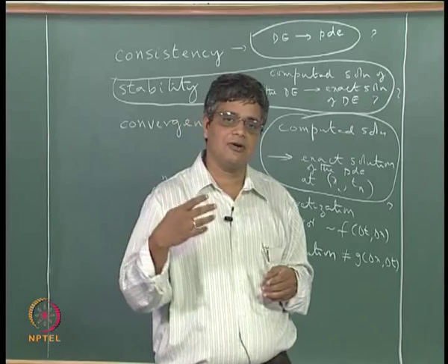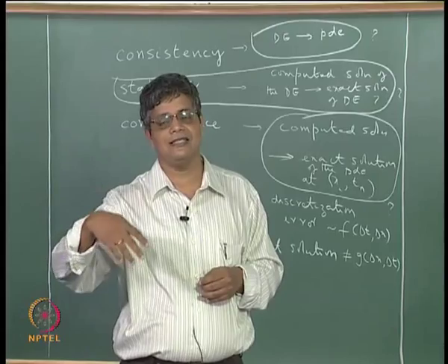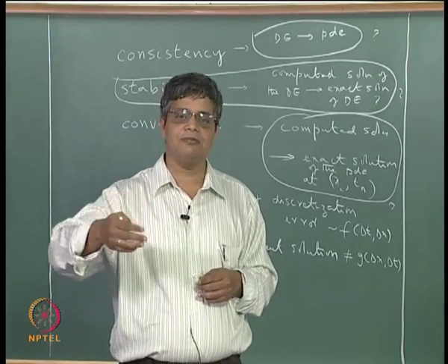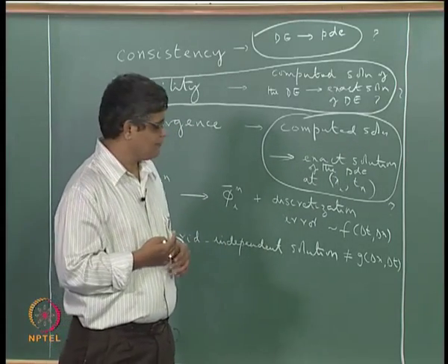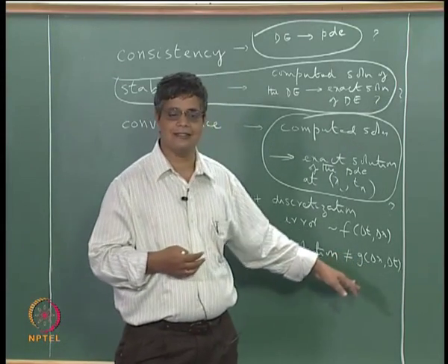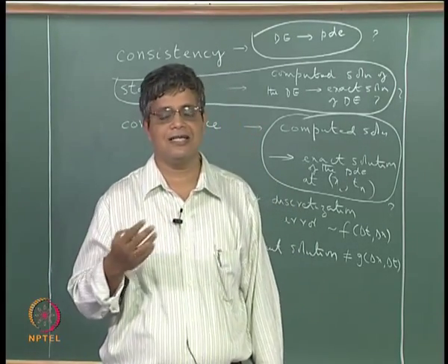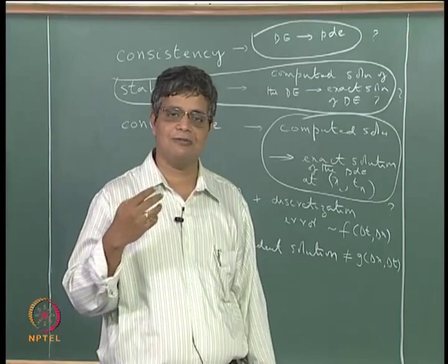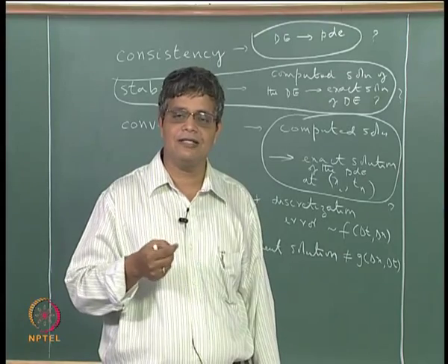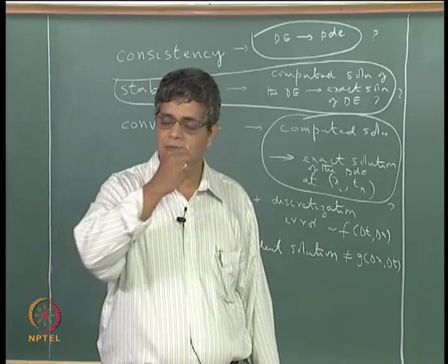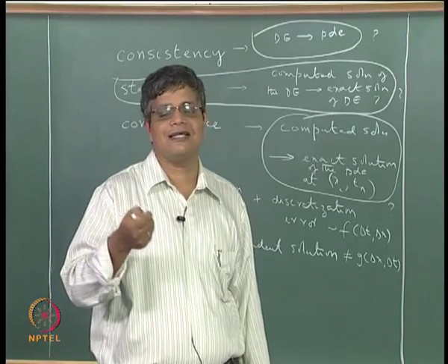But if you did not have any constraints on the computing resources, then you could make it as high as possible, and as you keep on increasing the grid size or the number of grid points, and as you keep on decreasing the delta x and delta t, then the parameter that is of interest to you, for example if you are looking at the pressure gradient, pressure drop in that particular duct for a given flow rate. Okay. So in such a case you will find that after some number of grid points, the computed pressure gradient does not really change much.